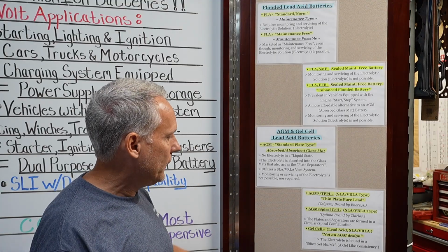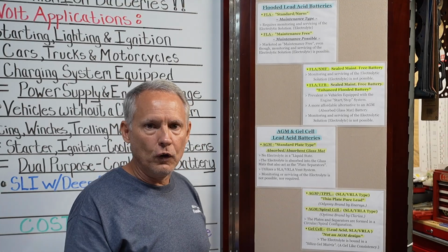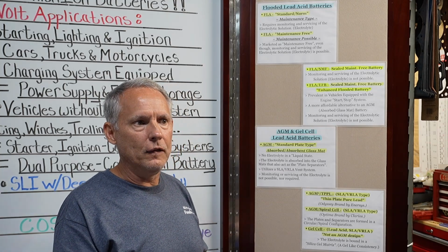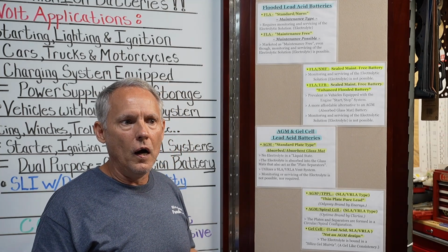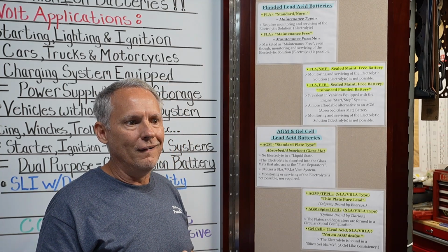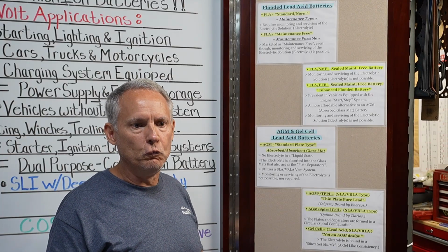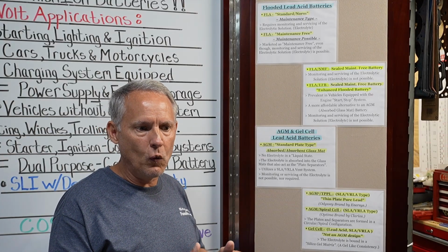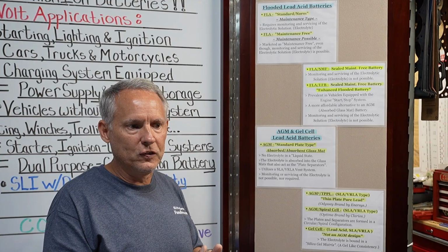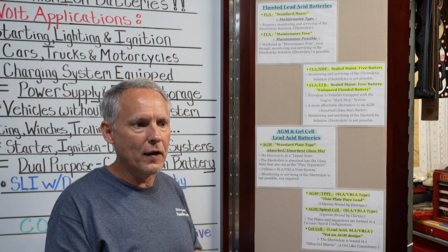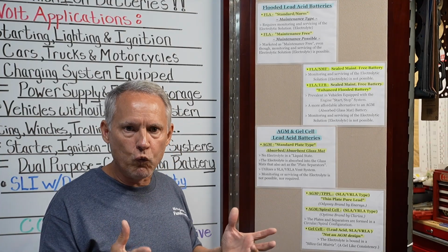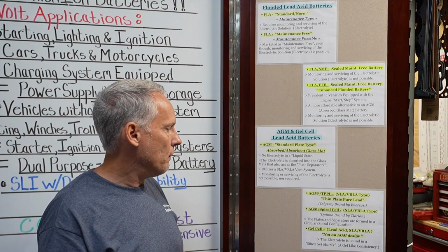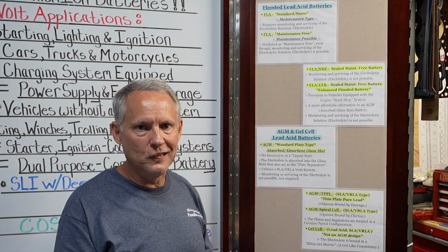The idea behind the electrolyte not being in a liquid state is that there's less chance of leakage, spillage, corrosion on terminals where the actual outgassing or maybe a small leak around the actual terminals on the battery has caused corrosion, damage. They tend to be very vibration resistant.